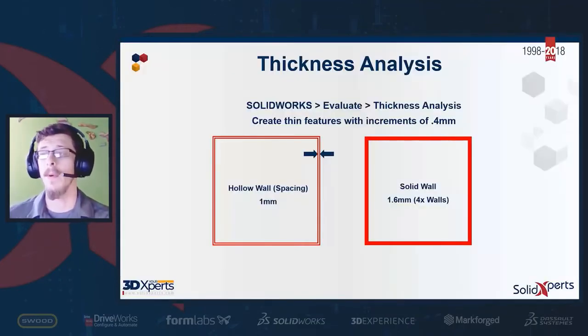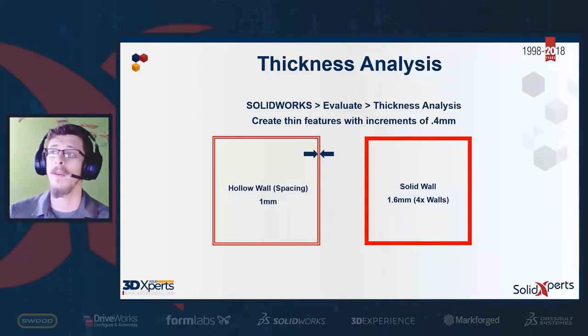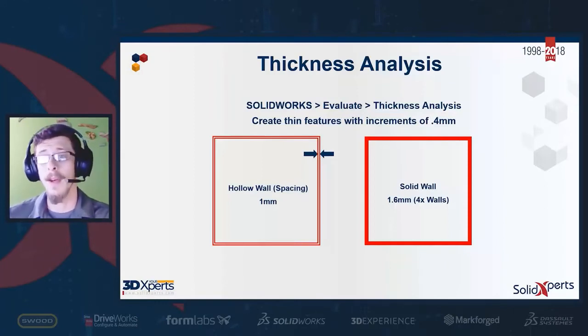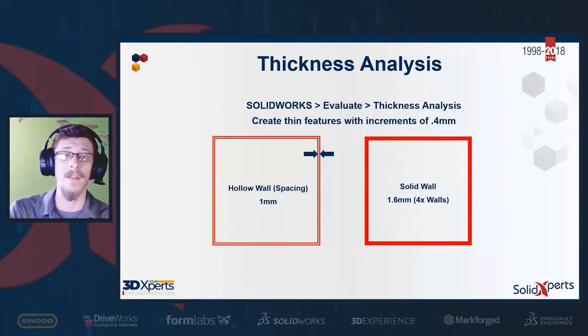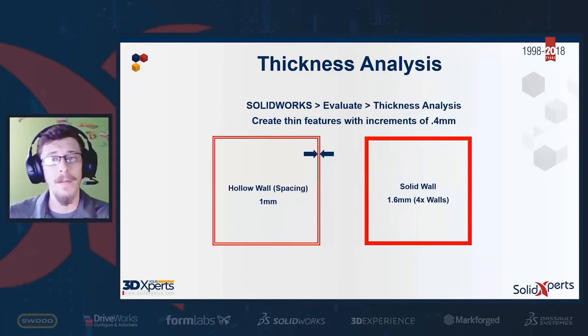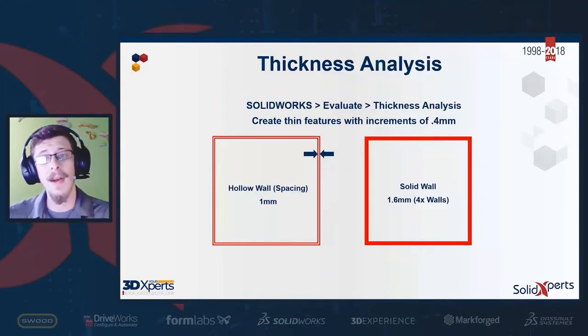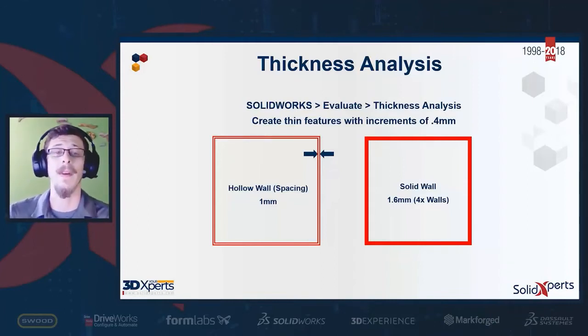Now, I've talked a lot about the support overhangs and angles and faces and how to accommodate those, but let's go back to those nozzle sizes. So again, the most common nozzle size is going to be 0.4 millimeters. And there are manufacturers and brands that use a 0.6, 0.8, something a little bit smaller like a 0.2, all over. But again, 0.4 millimeters seems to be a consistent size nozzle manufacturers use. Now, 0.4 millimeters is again a good mix because it deposits a decent amount of material, but can still be very accurate in designs.